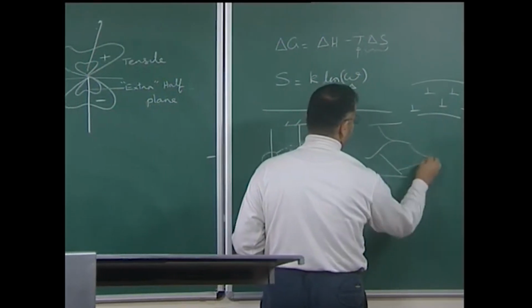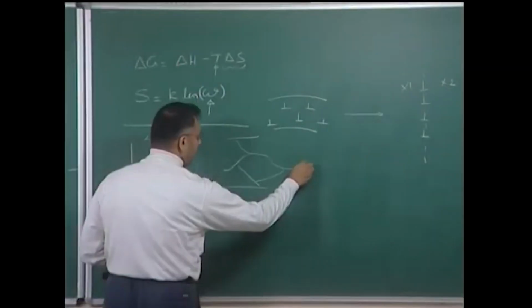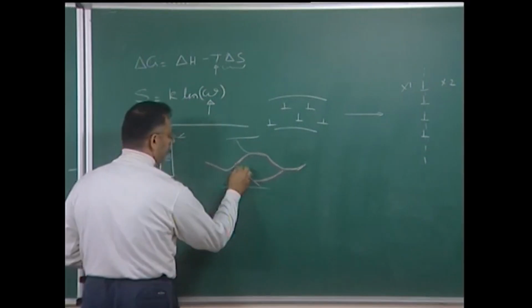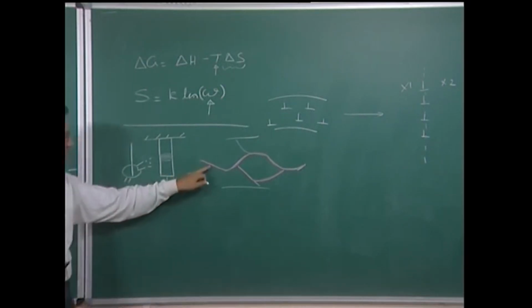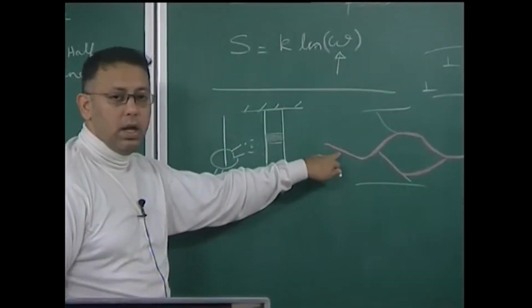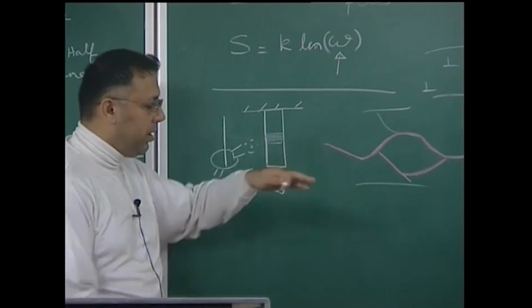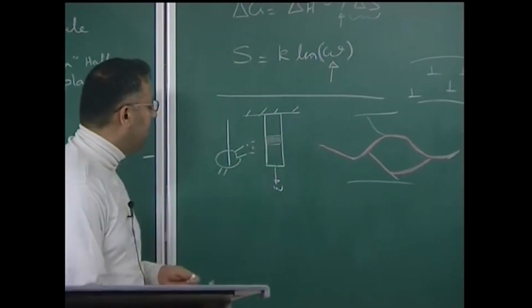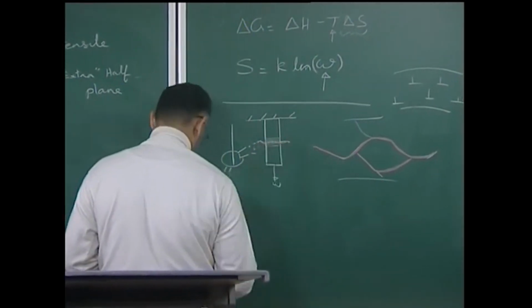The gallium selectively diffuses along the grain boundary, because now it has got a very high diffusivity along the grain boundaries and a very poor solubility. When a layer of gallium segregation takes place at the grain boundary, what can happen is that, so this is of course multi-layer segregation which I am showing here by red color, then gallium being almost liquid like at the temperatures we are talking here, the grain boundary debonds, and therefore this material will fail by these two parts of the material actually separating out here.